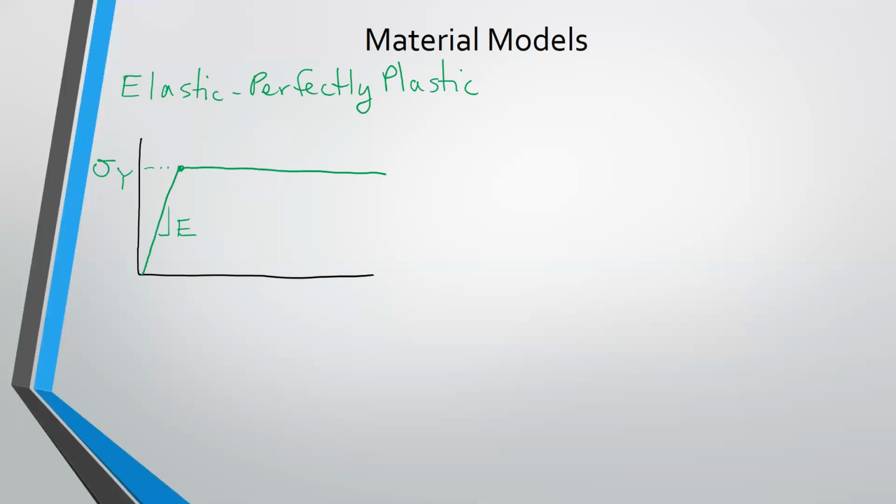Okay. So if you were to load in, say, a displacement control, which means you're continuously putting more strain into this material, you first follow up this curve in the linear portion, and then you move across to the right. And at some point, at some strain value, so this is strain and this is stress, you might decide that you want to unload the specimen. Okay, so it's carrying a certain amount of load. We might want to unload it to zero load. Say we're done testing it.